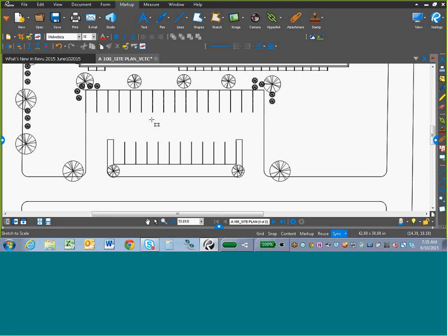I'm going to use my rectangle, and I will say that this is one of the tools that I had to play around with a little bit, because when you first make that initial mouse click to drop where your sketch is going to go, you get this dialog box. It gives you the ability to either manually enter your dimensions, or you can simply drag to get to your dimensions that way. I'm going to type in those dimensions, and if I wanted to, I could hit rotation. To close this off, I'm just going to hit enter.